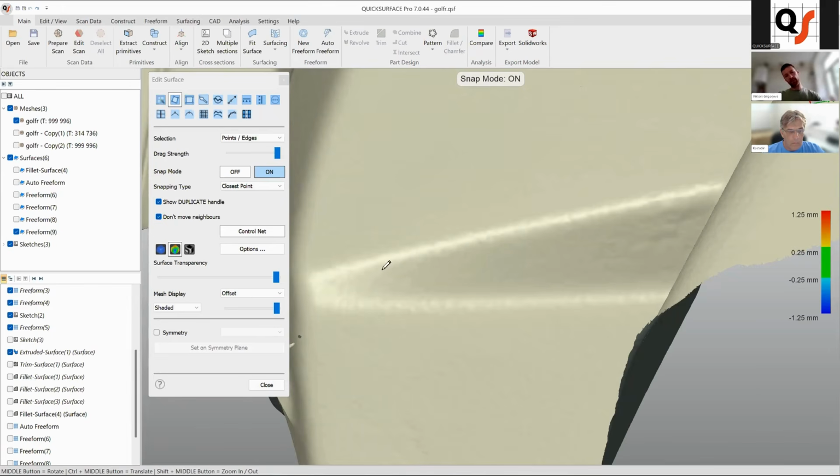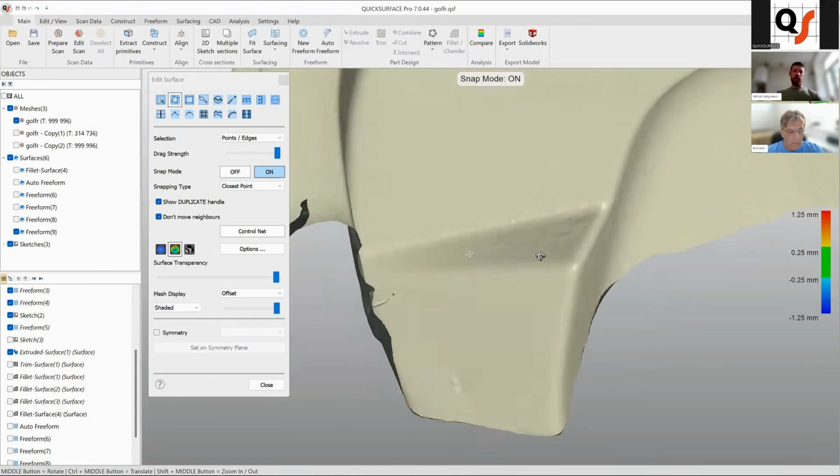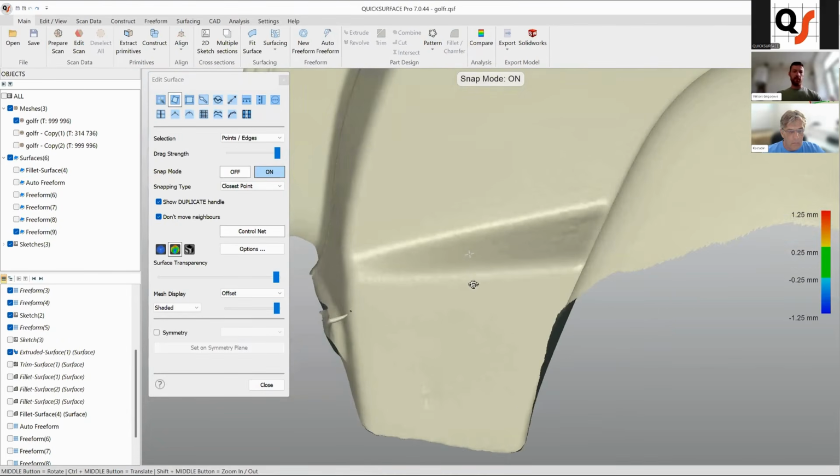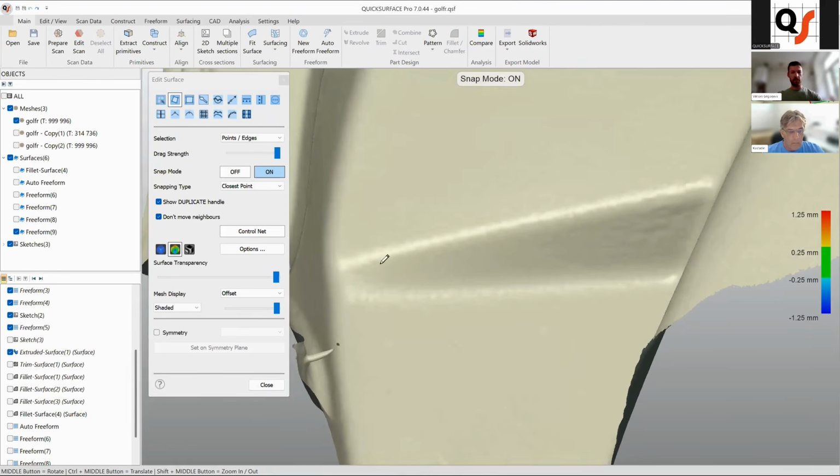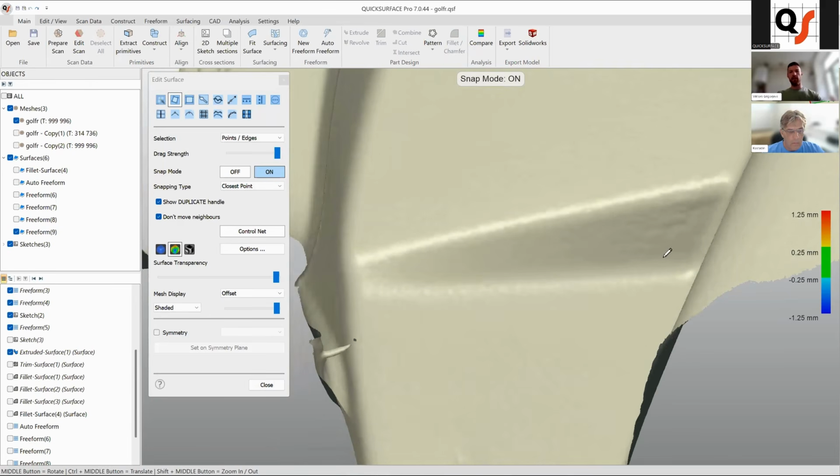And this would be extremely difficult to reverse engineer with some like casual sketches. Because if you have like a completely triangular corner, it will create degenerate surface and you won't have any smoothness there. Basically, you need to define oversized patch of surface and then trim it to have a good resulting surface.